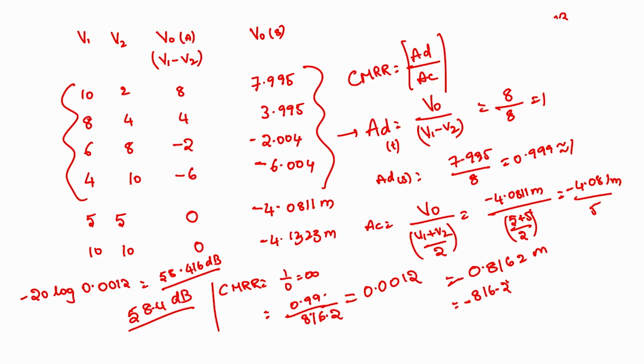right. Suppose we are taking a different op amp, I do not know what op amp or what make we have considered in the simulation. We have simply used the op amp that is available there. So this is how we generally calculate the dB of our differential amplifier. Moreover, since we are not going to apply almost a common mode signal, and even if we apply, we are getting somewhere in the milli, since it is negligible, we can simply go with a difference amplifier itself.